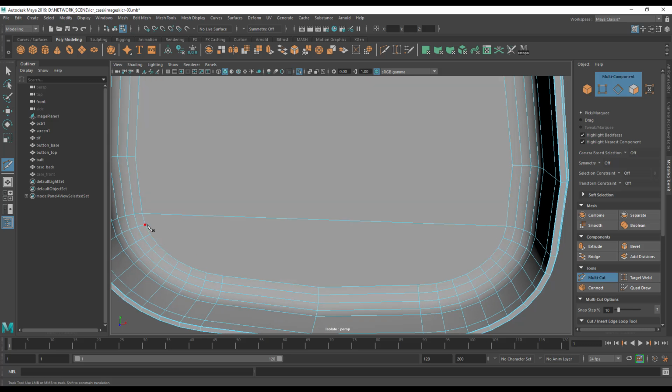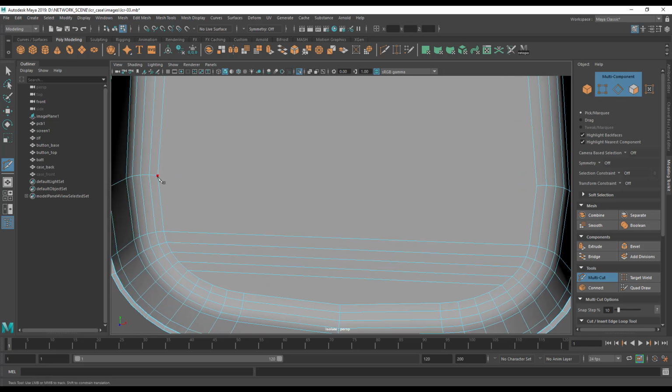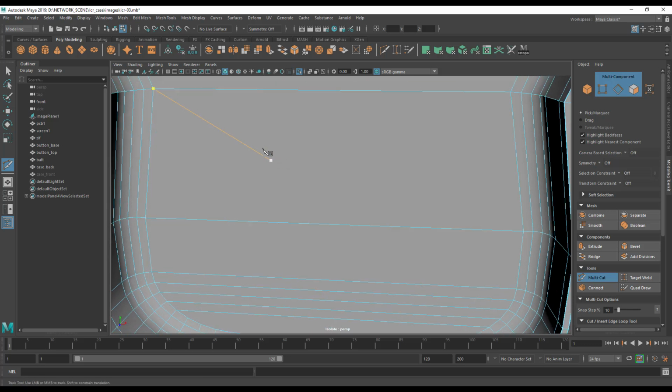because it would be necessary if I was going to texture this thing, if I was going to use any of Maya's more advanced tools, if I was going to present this to somebody else to work on. Then certainly I would not give them a model with a screaming great n-gon in the middle of it. And I'll just show you how to quickly retopologize this so it works. But for 3D printing purposes, you can get away with not doing this.